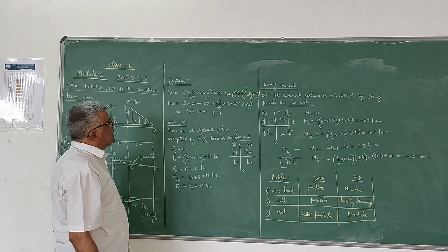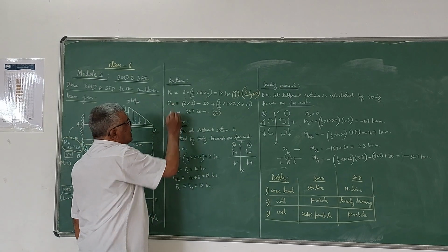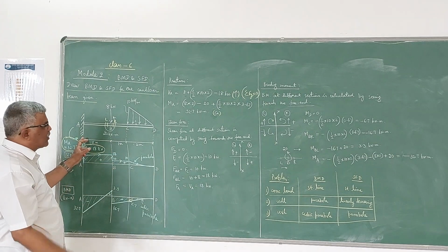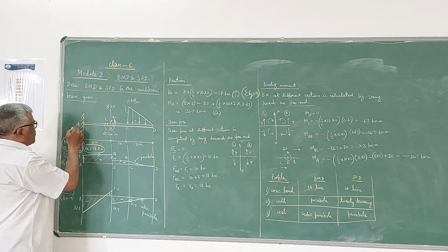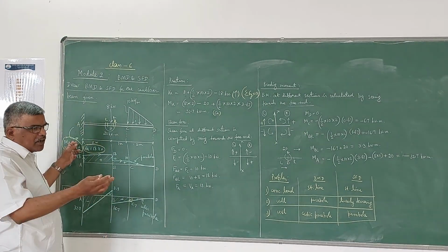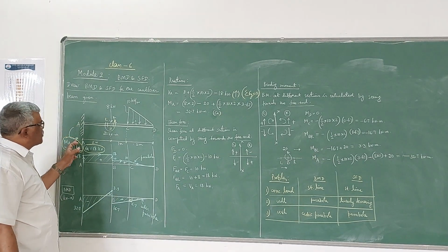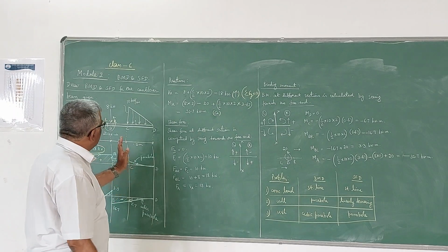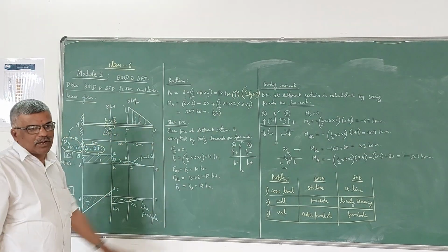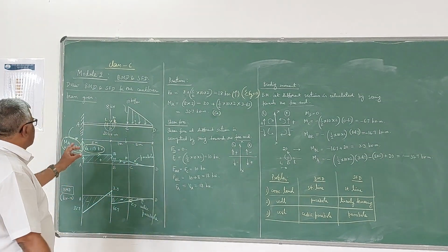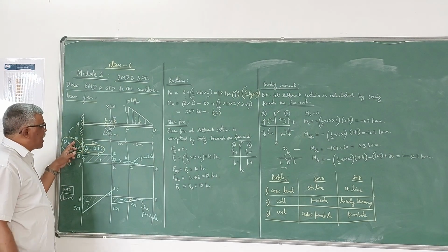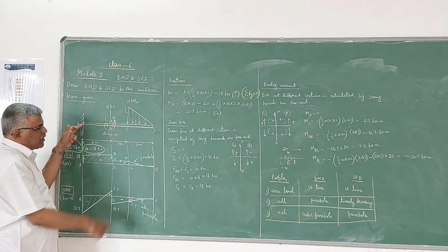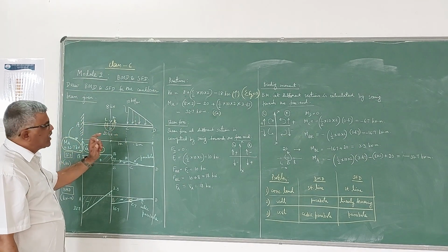Now the second equation is the moment equation, which is nothing but sigma MA is equal to 0. Or in other words, to find this reaction MA, I have already told that the reactive moment should be equal to the algebraic sum of the moments caused due to the externally applied loads taken about that point. Now since the reactive moment develops at A, this MA value will be equal to the sum of all these clockwise moments and also the external moment given in the problem.